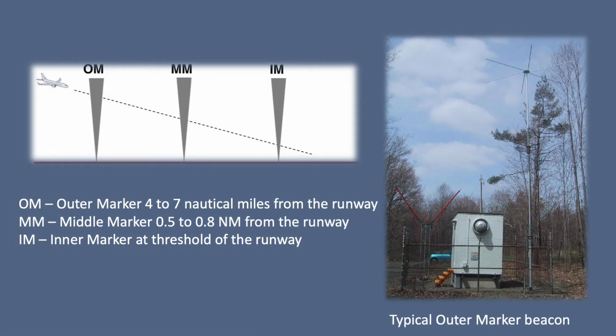The pilot must descend at the correct rate vertically to land at the end of the runway. He or she must also have correct horizontal alignment to the runway centerline. The ILS system has three key marker beacons to assist with distance from the runway. They have associated ground transmission stations.